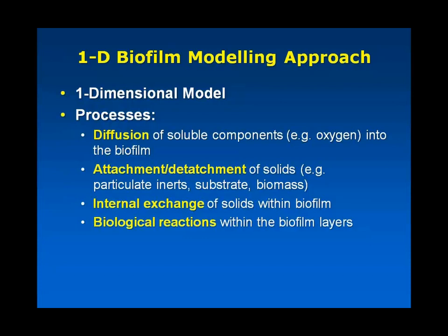So if you have growth of new biomass inside that biofilm, it can grow up and push out into outer layers. And then on top of all of that, we of course have the biological reactions, just like you would have for all of our activated sludge models. They're going on in each one of those biofilm layers. And so what you can do is plot the gradient of the concentrations through those biofilm layers at any point when you're using your model, and I'm going to illustrate that when we get to our demonstration later on.